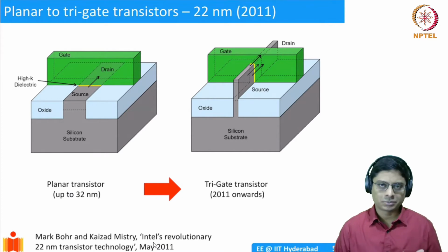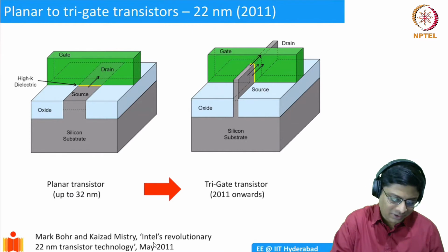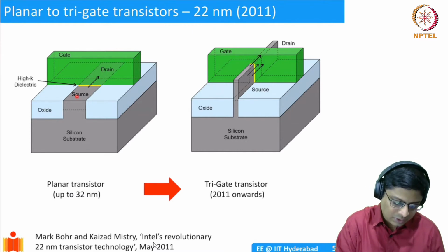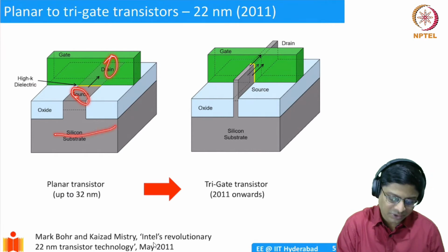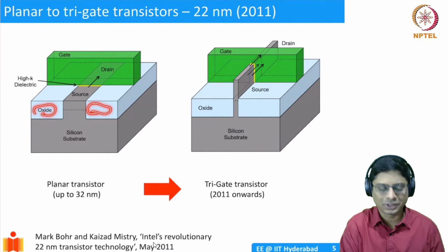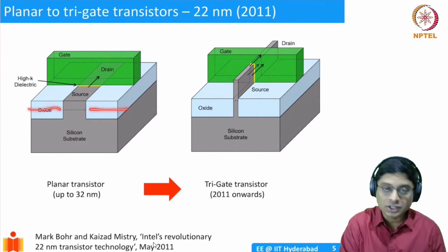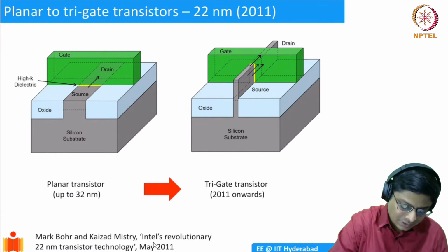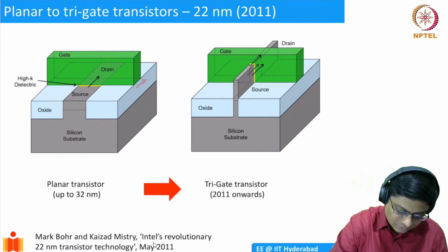The reason they're called planar transistors is that we are familiar with the structure of a transistor. It's just rotated. So basically, you have the source, you have the drain, and you have the substrate. Okay, and this is the field oxide that we talked about, or shallow trench isolation, whatever it is. It is the isolation between two transistors. So where is your channel length? Channel length is here. This is the length of the channel, and this is the width of the transistor.